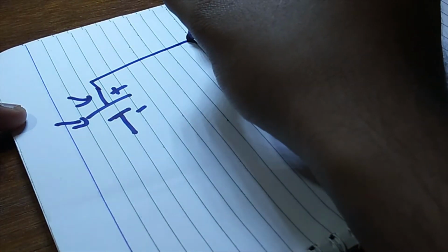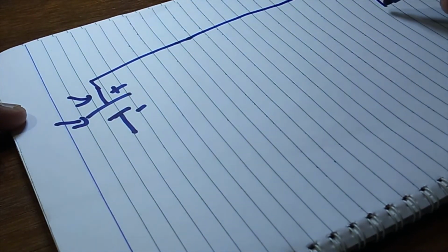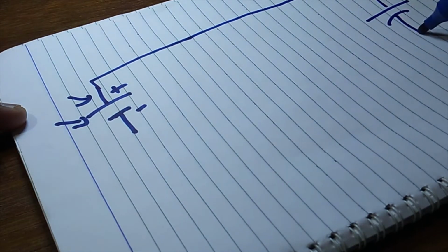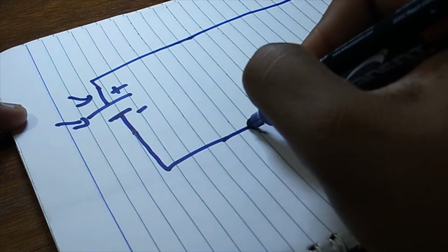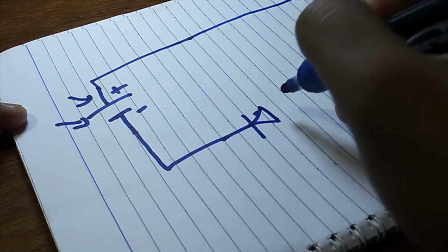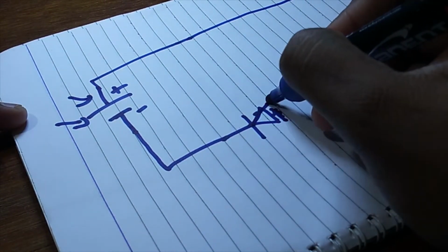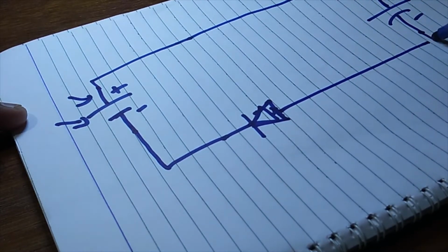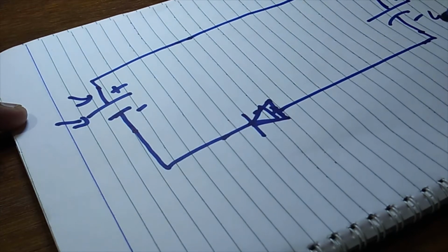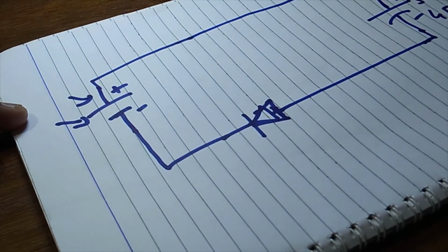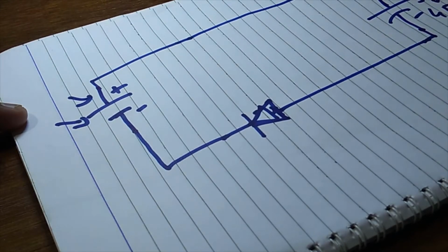The solar panel goes here, and it charges the super cap. I'm going to draw an electrolytic cap, if I'm not mistaken. This is the right symbol, and obviously this has to be charged via a reverse blocking diode, right? The diode that we just saw. This is how the charging of the super cap will be. This is 4 farad, 5.5 volts, and this guy is a solar panel.